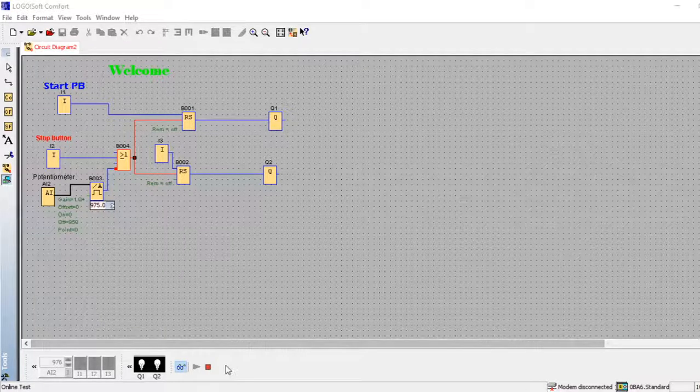So this system can also be used to control pumps. If you have a pump at home that just runs at maximum speed, you can use a VFD to control the speed of the pump, so that it doesn't just run at maximum speed, because it can easily overheat and it can easily burn out.